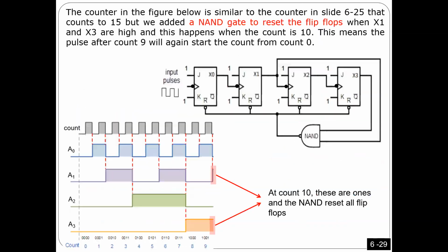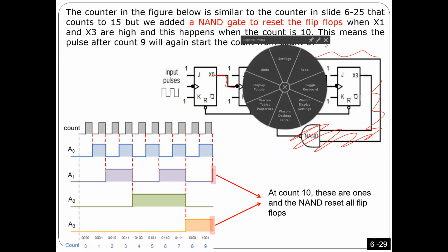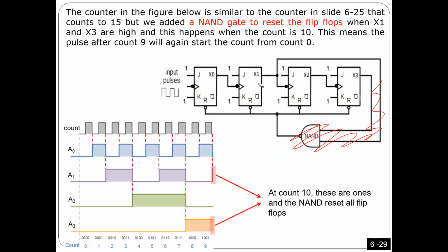So to design this one, this is without this part. If I just cancel this part here, this becomes a 4-bit counter, as I explained before. You can see I connect J and K to 1, 1, so they are toggling, and the output of one is the input to the next one. This is exactly everything I explained before. However, look here, this is the trick I made.